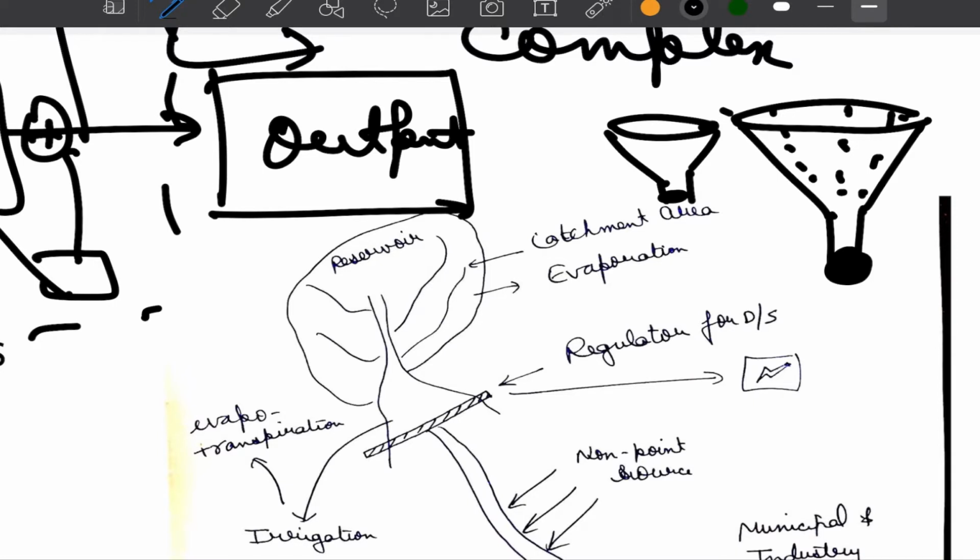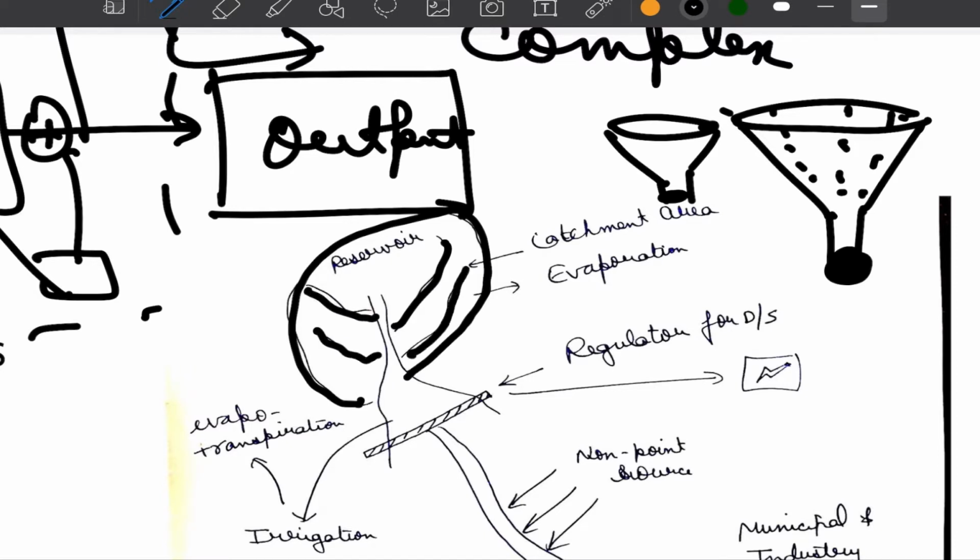So we call this a catchment, wherever we define this boundary, such that anything and everything happening within this catchment, at least in terms of inflows, would stay here, and through rivers, channels, or streams, this water would be taken to the main river. If you talk about river Ganges, we know that river Ganges has so many tributaries and distributaries. So when you try to draw a boundary around the Ganga river basin, you would end up visualizing the watershed that is being traced by river Ganges.